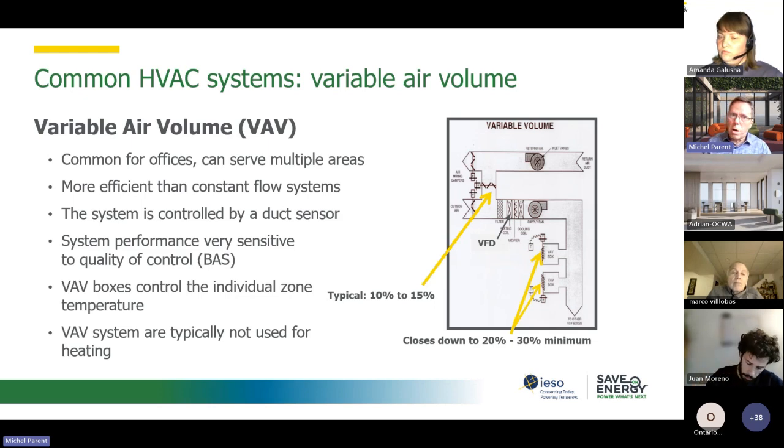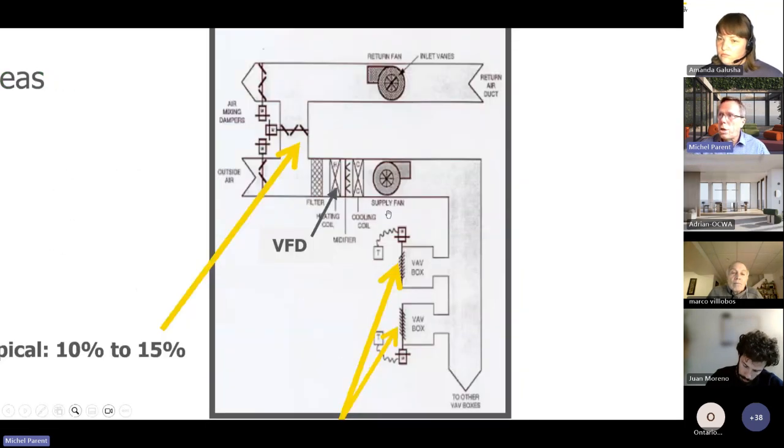And it's just like a makeup air unit. That means that the system right here is not designed to heat the building itself. It may have a reheat coil with fan-powered boxes at the end, but typically this heating coil and this cooling coil, they are not there. Actually, I should not say the cooling coil, but the heating coil is not there to heat the space because it's controlled by a